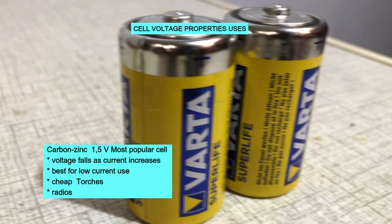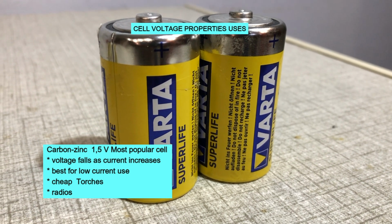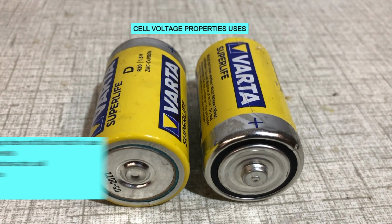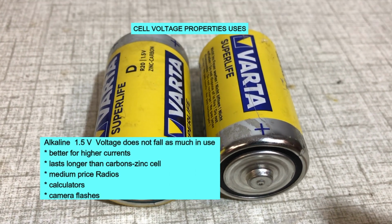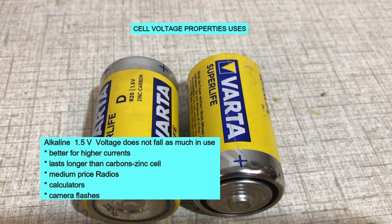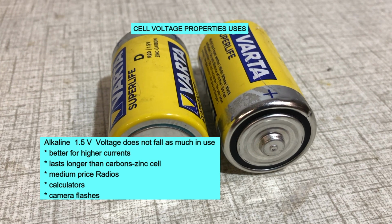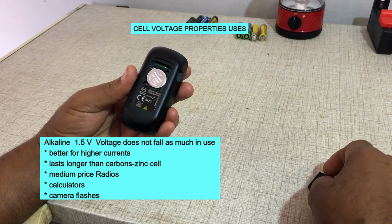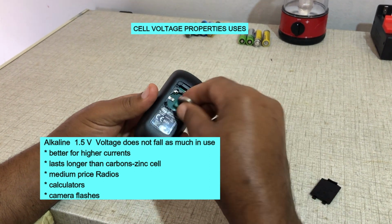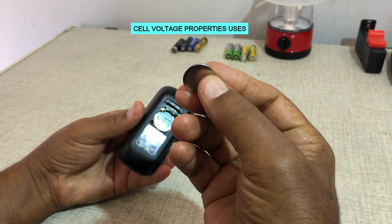Voltage falls as current increases, best for low current use. Cheap torches, radios. Alkaline: 1.5 V, voltage does not fall as much in use, better for higher currents, lasts longer than carbon zinc cell. Medium price, radios, calculators, camera flashes.